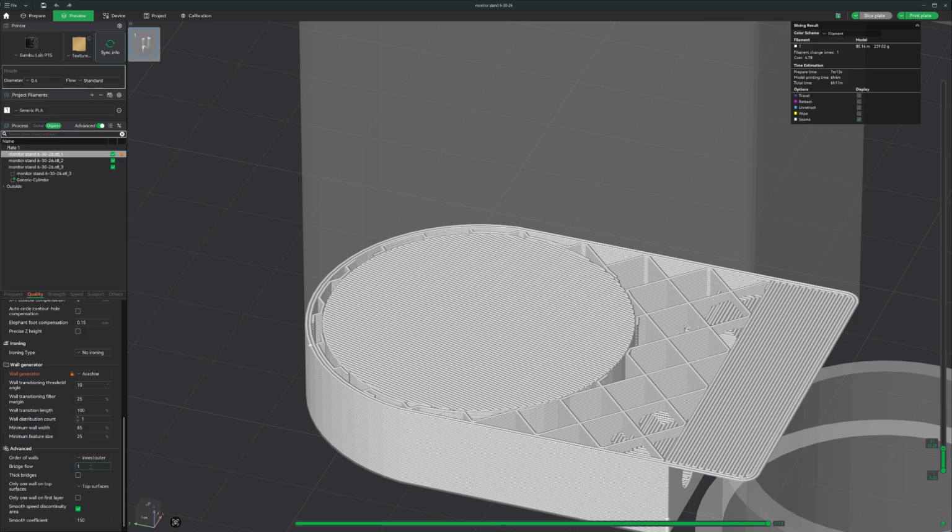you would change this down to 0.85 is what I would do, or 0.9, and somewhere in between there, I would add or subtract just a tiny bit from that general area. And you may have to print something once or twice, or just print the area of something once or twice, in order to get these settings down.